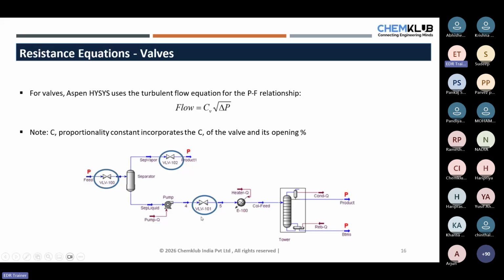While converting your steady state simulation to dynamic, you will see multiple valves which were not there before but are now part of your simulation scheme. Those valves are the ones providing resistance to the system, because of which the flow occurs through the system.